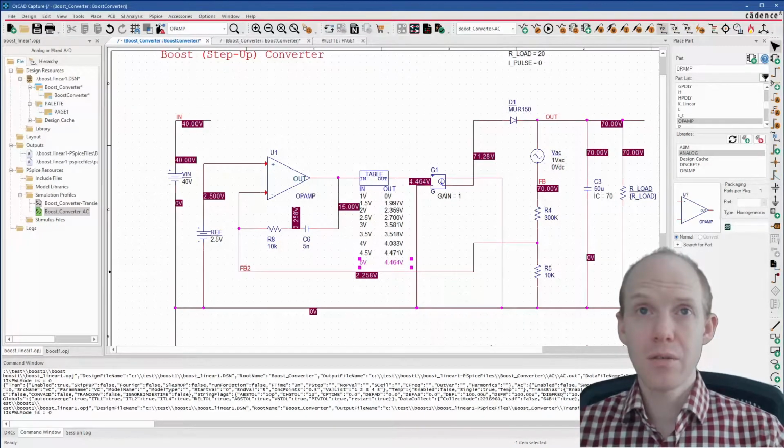So we're going to have to fiddle around with this circuit and try to get it into a position with our initial conditions where it's calculating a steady state bias point as its initial guess, which should make this output here in this table range, so maybe 3 or 4 volts.